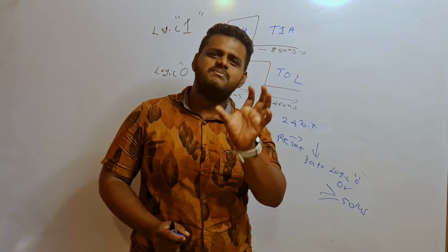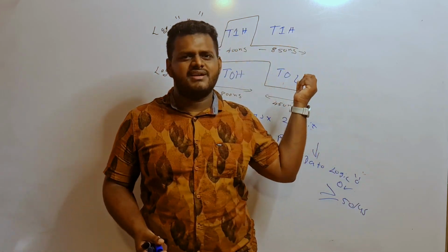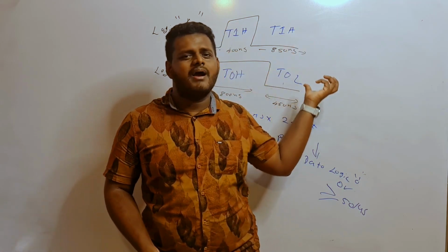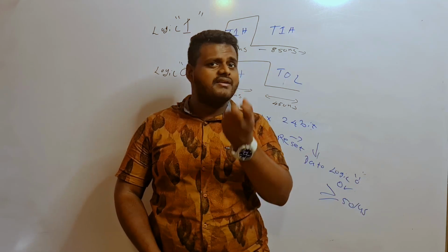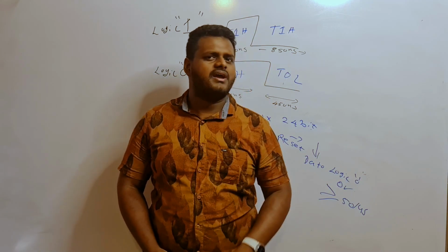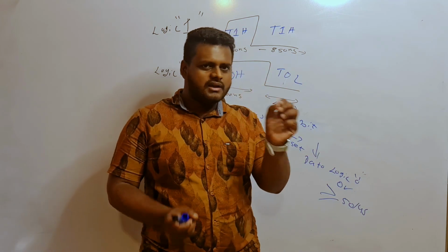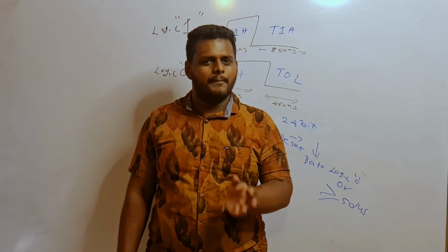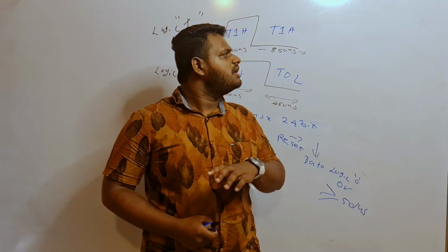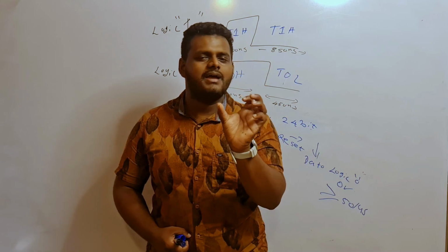Everything is mentioned in the datasheet, but the problem is you are looking at a lot of things on how to make this 400 nanosecond timing. But one instruction in a PIC microcontroller at 20 megahertz is 200 nanoseconds. So using 2 instruction cycles, we can produce 400 nanosecond timing. That's very simple. You can use port high, port low, or no operation instructions to produce that specific timing.